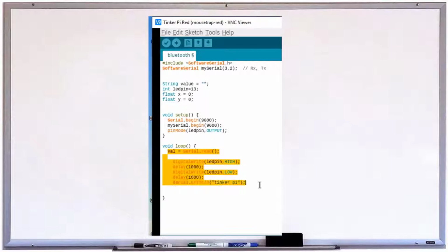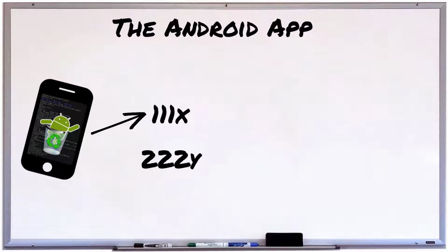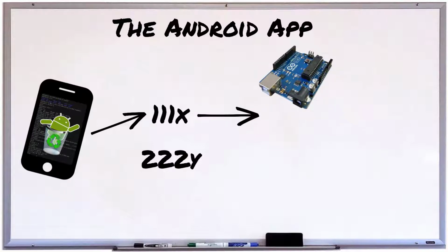We'll create a while loop that will continually check to see if anything has come across the serial pins 2 and 3 that we've hooked the Bluetooth module to. Remember that when we push the button, the phone will send the string 111X or 222Y. The X or Y at the end of the string will tell the Arduino whether the value it just read is from the X or Y axis.